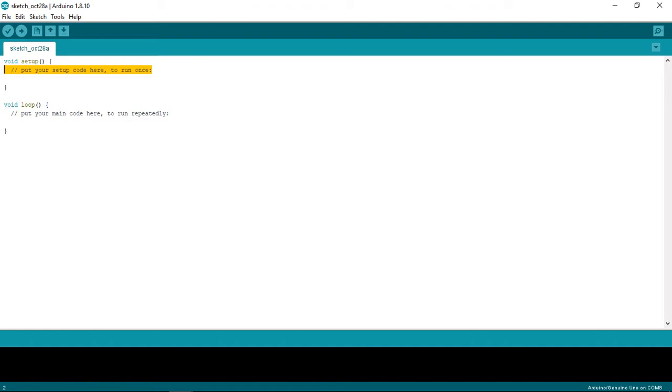Well, first of all, I define my pins. Pin mode. I'm using pin number 13 as output, since, as I said, pin number 13 has a built-in LED connected. That's why I'm using it. We can also call it LED_BUILTIN. It's known to the Arduino IDE, so if you write LED_BUILTIN, it means pin number 13. So I'll just write 13 for simplicity.